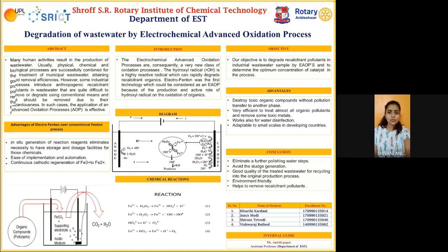There are various AOPs, among which electro-Fenton has gained much attention nowadays. Short reaction time, formation of hydroxyl radicals through in situ electro-regeneration of H2O2 and Fe2+, no transportation cost of H2O2, inexpensive Fenton reagents, etc. are some of the reasons behind choosing the electro-Fenton process in the present study.